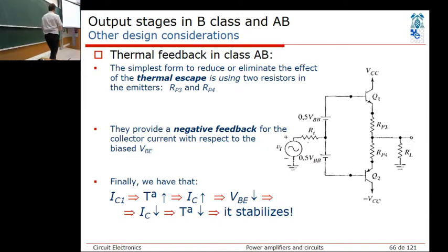Okay, and then we have a very simple way of reducing, well, not necessarily eliminating the effect. If you put a couple of these small resistors on the emitter, then the effect is about the same as a standard voltage follower case.